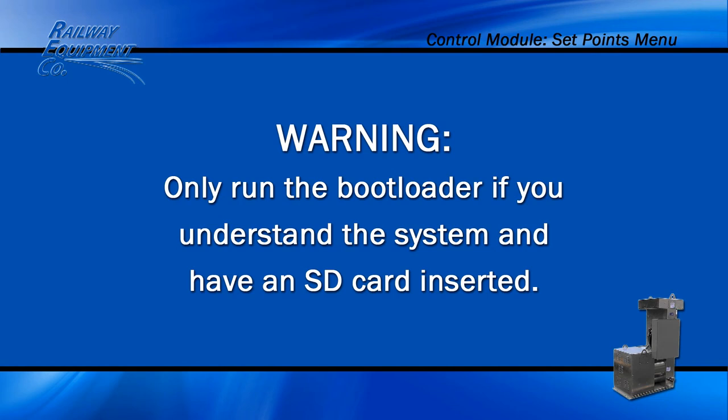Leave the setting as Do Not Run Bootloader unless you know how to work the system and have an SD card inserted. Otherwise, you will be locked out of the system.